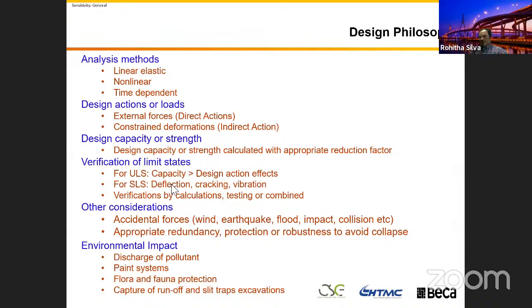So you can't say it's good for traffic, but it's not good for wind and earthquake. You can't design any structural element like that. And then on the serviceability limit state side, you need to make sure your deflection, cracking, and vibration are looked after, like deflection and vibration are more or less combined in the bridge design.